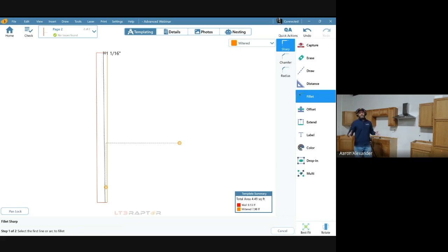Now I understand not all stone is flat, right? Maybe you want to know if that countertop is dipped at all or anything like that. We do give you 6 of these blocks, and I have heard of people wanting to know what the countertop is doing. So you could put multiple blocks across there, shoot the 1/2 inch line on all of them, and see how flat our countertop actually got installed, how flat that slab was that we cut it out of, right? Here I'm just going to demonstrate using 2 points, as if we assume this is level and flat, okay?